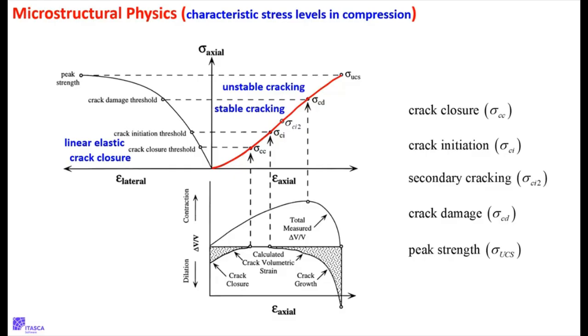And so you can actually hear this during a test. You can hear little snaps and pops. And there's almost no snaps and pops going on here. You're basically just closing up those initial gaps. Okay, so crack closure. Then you keep going a little further, so you're just applying strain and monitoring the force. It's getting higher and higher in a linear fashion, and you're pretty much not getting anything happening. That's why it's linear. There's pretty much no micro cracks forming, and everything's been closed up.